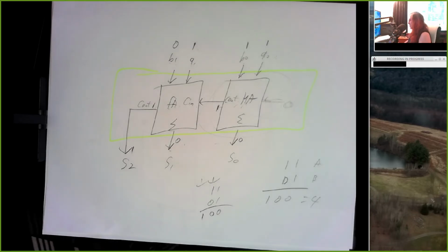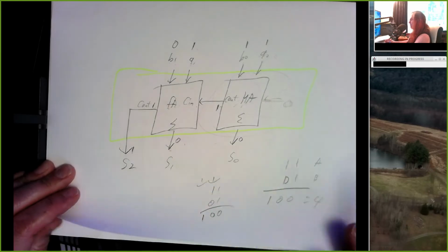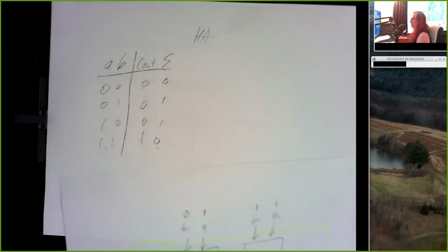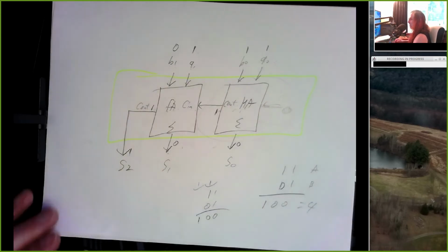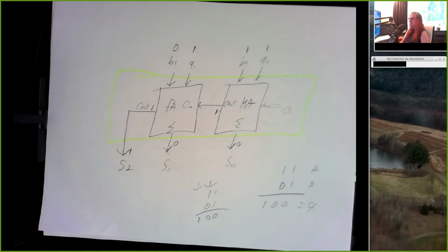And same thing on tests. I might ask you about a half adder. I might ask you to write the truth table for a half adder or sketch a schematic for a half adder and such. So make sure you at least understand how that would be used, even if you don't use it.